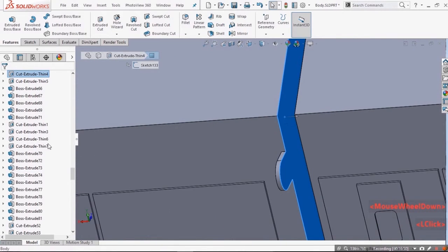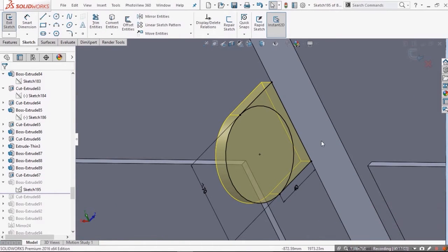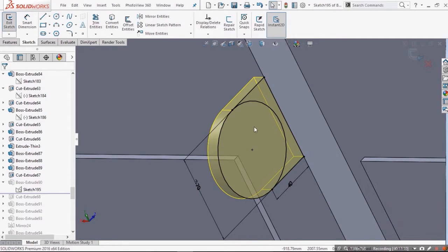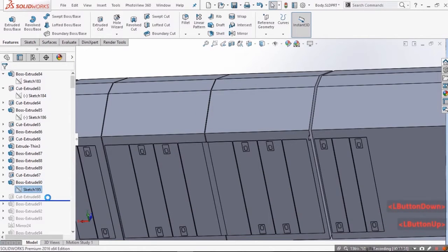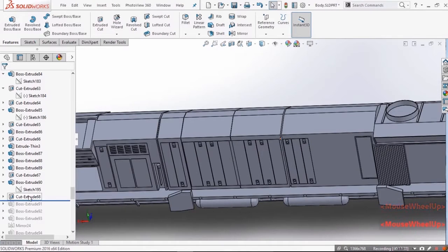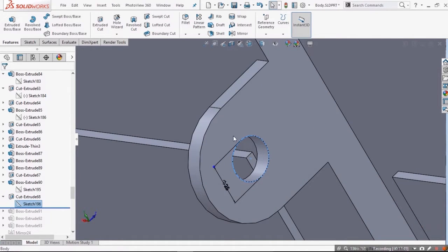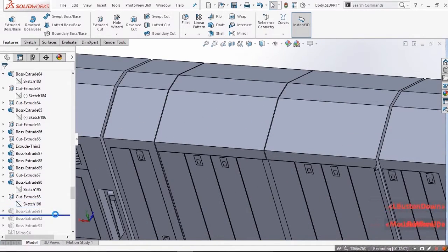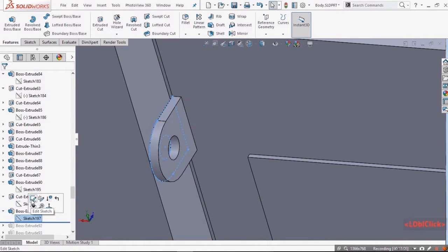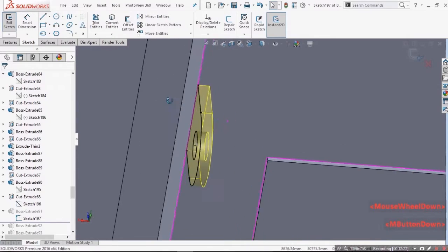On this surface I have made this sketch, which visibly shows a clamp kind of feature. So now to cut the hole inside it, you can use either of the surfaces of the newly made feature, draw a circle and just apply extrude cut. Here I have used the Convert Entities feature, which converts the boundaries of the selected surface into sketch entities. Another time-saving catch.